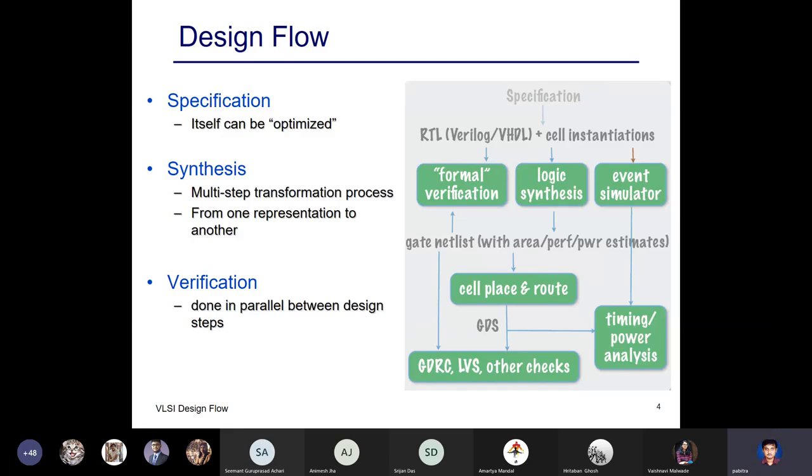Usually Xilinx, there will be Xilinx and other boards which make these FPGAs. So what we'll do is that after you have your compiled Verilog output, you download it to the FPGA. That means you kind of program the FPGA, and then you have your hardware ready. You download to the FPGA, you run the FPGA, you see the result. And these FPGA boards will have ports which you can connect to your computer, and it will download from your computer with some interface and applications set there.